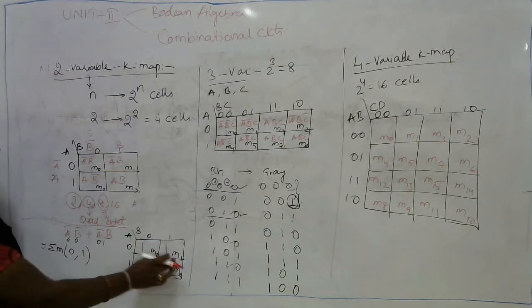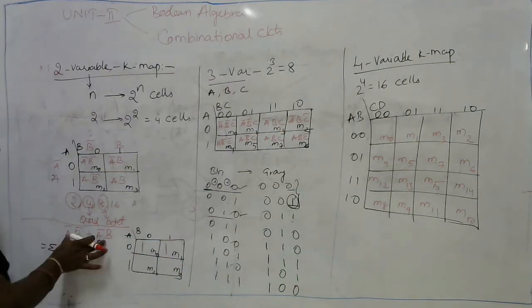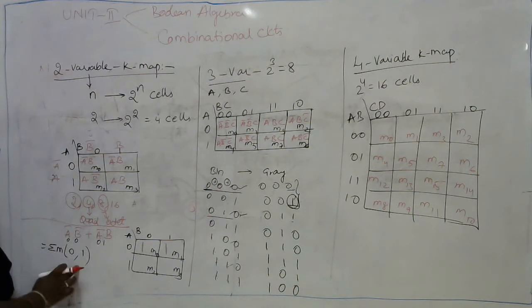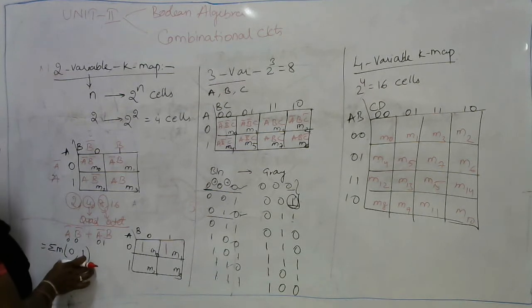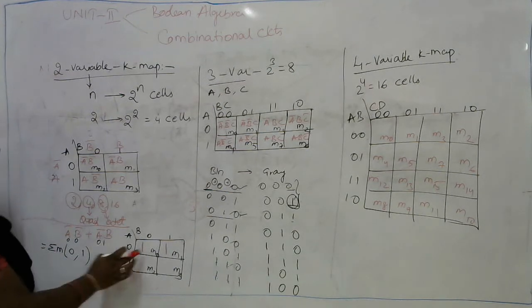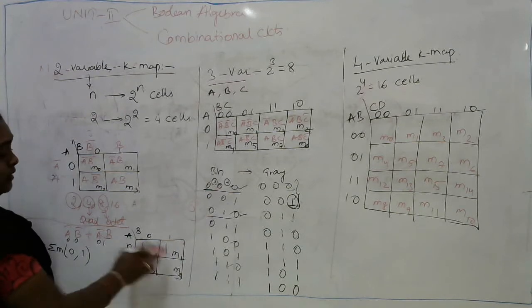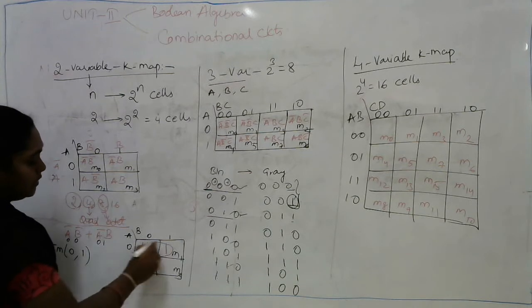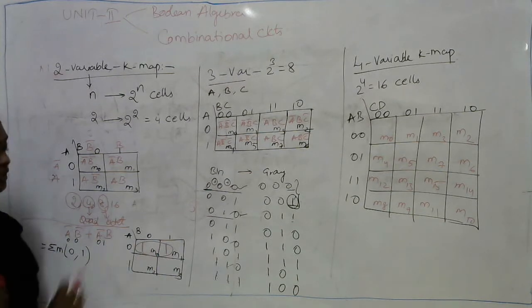Now this is the plotting of the K-map. From the given expression, if it is in terms of variables, convert it into sigma m or pi m terms, that is, either an SOP or a POS expression. Whatever minterms we got from that expression, plot those numbers in the K-map. As we have just discussed, these two cells are adjacent cells. Just combine these two cells, just join these two cells.